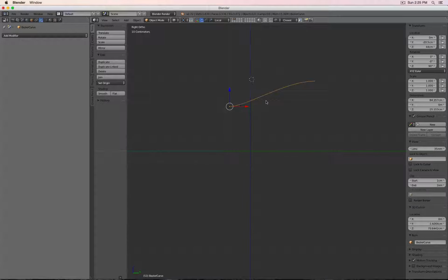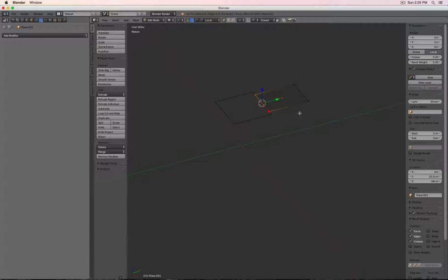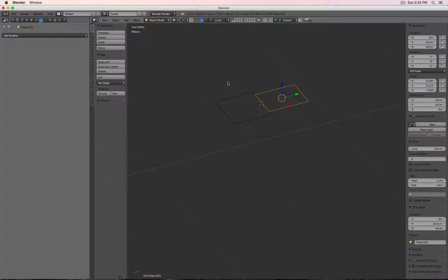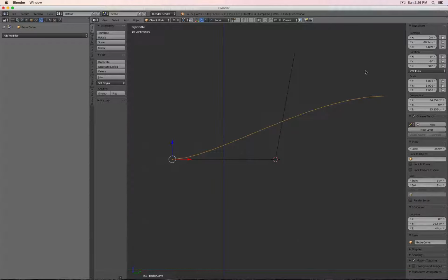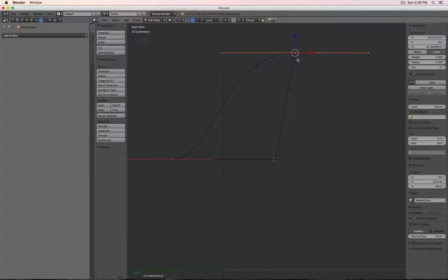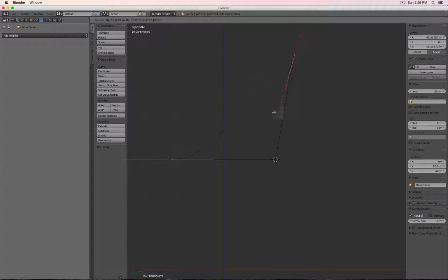Okay, so that is actually pretty nice and very helpful, because what I can do now is here, select these 2 points, enter edit and then leave edit mode, set origin to 3D cursor, and for example from a side now, I could rotate this one up and use this somewhat as a reference for my Bezier curve to understand where maybe I have to put all those control points and the handles, and I can rotate this one and there.